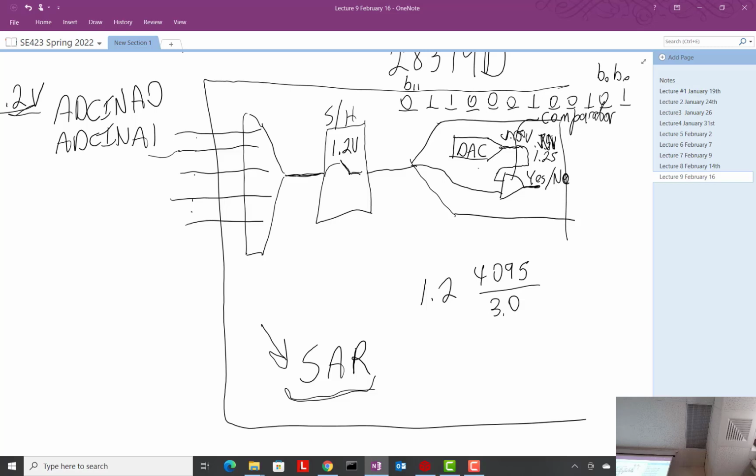Also, we're going to be playing around with other things, like the PWM too. We just write to the PWM and the duty cycle changes immediately. Well, it's not actually immediately, but it's really fast. When I say really fast, we're talking nanoseconds. When we're talking kind of slow, like this ADC, we're talking microseconds.